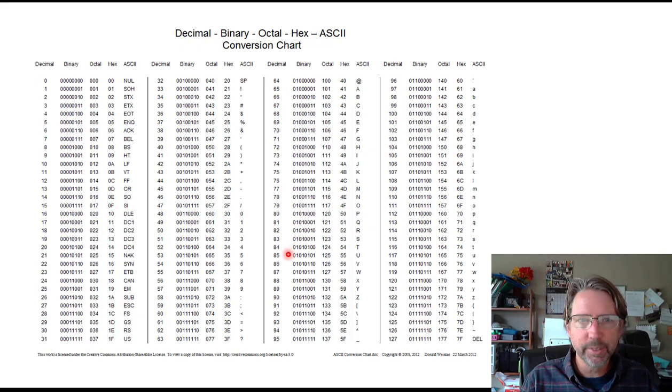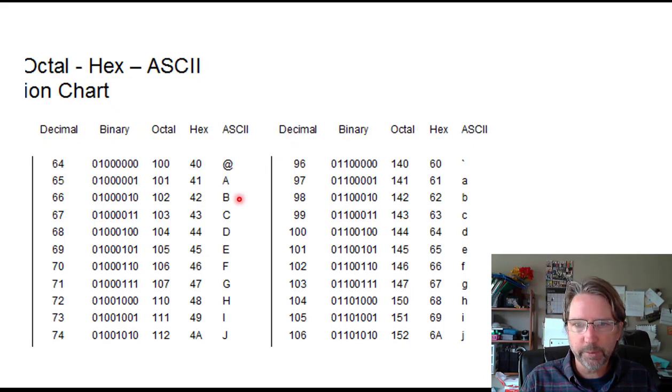So you can send numbers. This is how your serial port works when you do serial.print in the Arduino. It converts your letters into numbers and sends the numbers, and then the serial terminal on your computer converts the numbers back into characters using this lookup table. Just to zoom in a little more, we can see the capital letters start with 65 and they go in alphabetical order. Lowercase starts with 97 and goes up, and there are quite a few non-printable and control characters and things too, especially in the lower numbers.